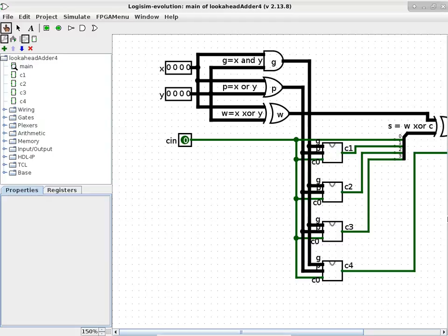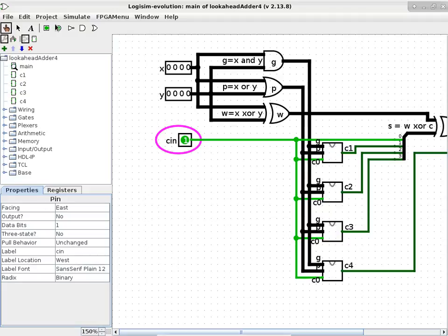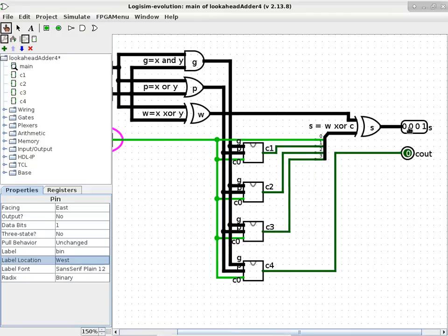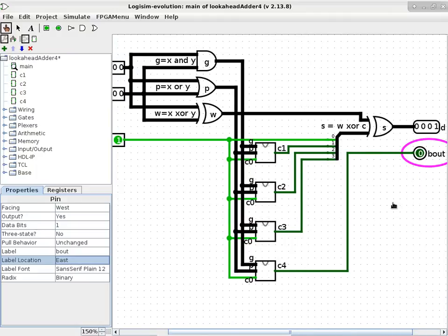All right, so the way you change this into a subtractor, the most difficult part is changing these guys. So that C in becomes B in, borrow in, and this becomes the difference, which is not the sum, right? And this becomes borrow out instead of carry out. Okay, so I think I got all of those taken care of.